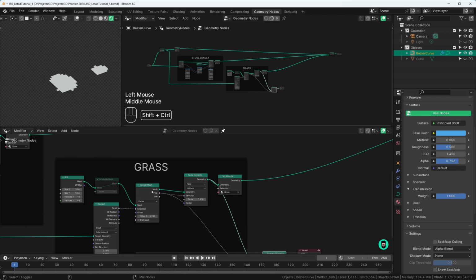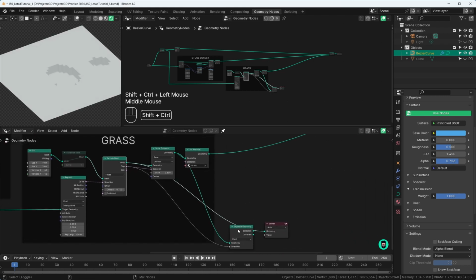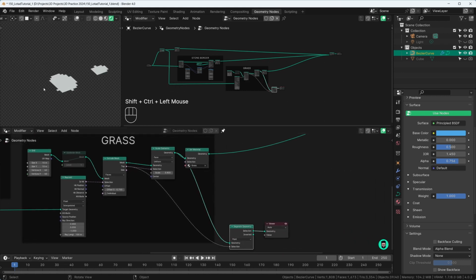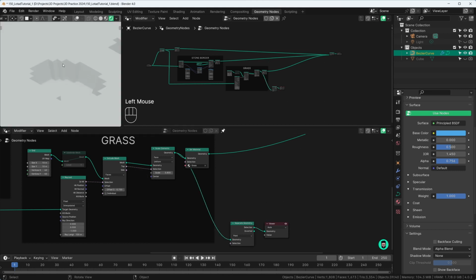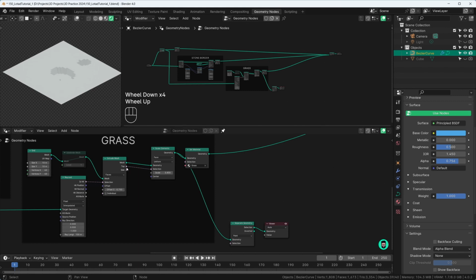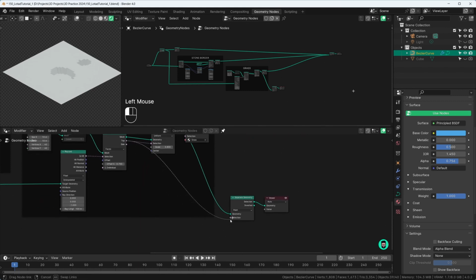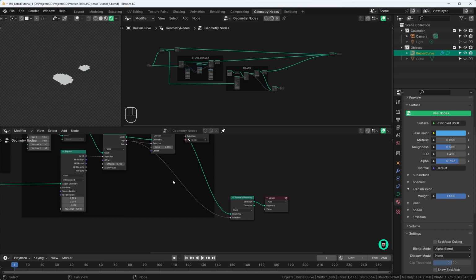So if we select onto any node, you can just see it live on the viewer node. Now if you notice, we added this extrude mesh node to this selection, and now it only shows the area or the faces which are extruded. So if we remove this selection, you will get all of this, and if we just add the top, you will get just this selection.